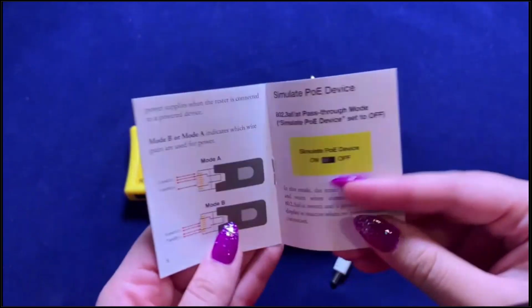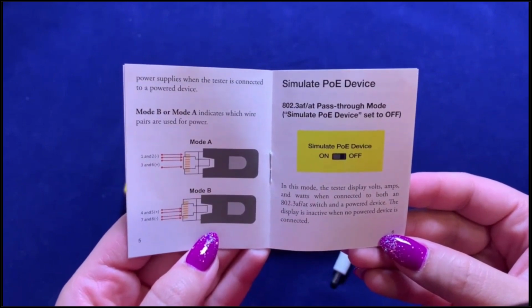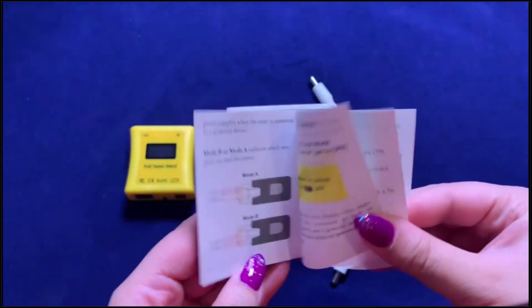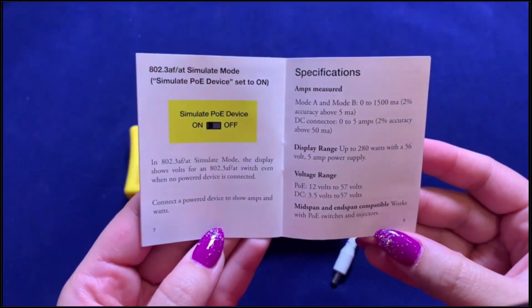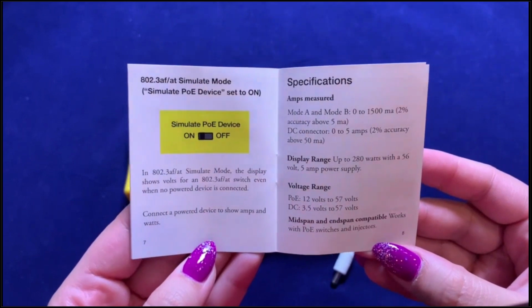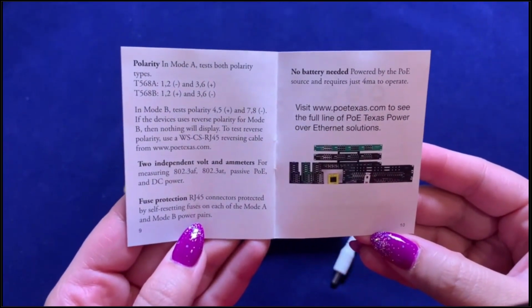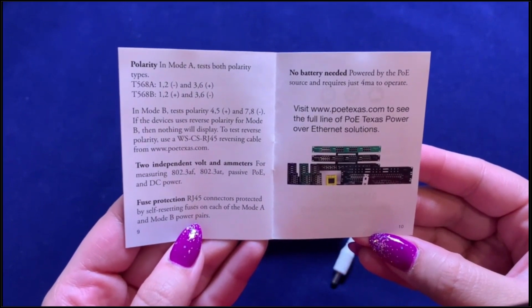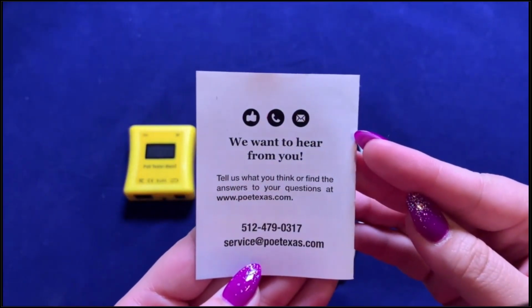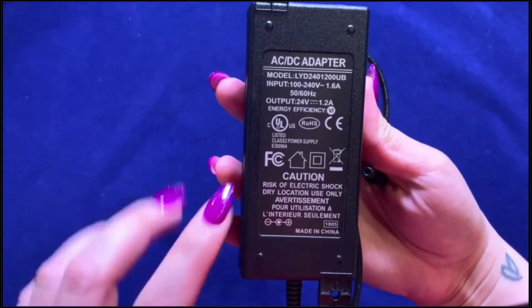It can read a PoE voltage range of 12 to 57 volts and a DC range of 3.5 to 56 volts. It is rated for 802.3 BT readings, so for mode A and B, it can read 0 to 1500 milliamps with a 2% accuracy, and the DC connector can read 0 to 5 amps, also with a 2% accuracy. When testing mode A, this Gen 2 can detect both polarity types. However, if using reverse mode B, you will need additional cable accessories.